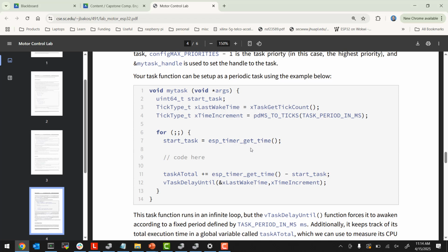Well, FreeRTOS has hooks. You can have it call a function whenever a task becomes ready or a task ends. Unfortunately, Arduino prevents you from using those, because the only way to use those is to use the native operating system and compile it with the hooks. You might say, compile an operating system? Why would you do that? Well, real-time operating systems are not like Linux. You actually compile them every time you change your code.